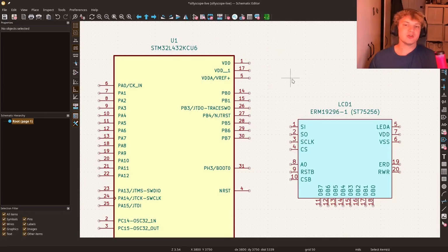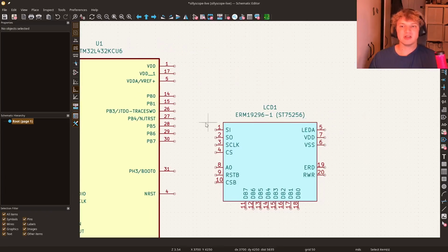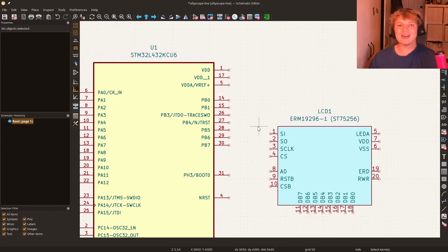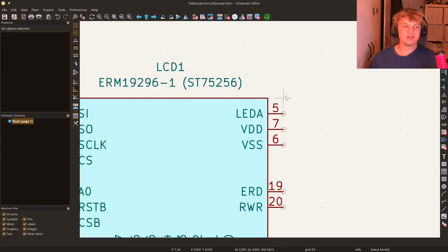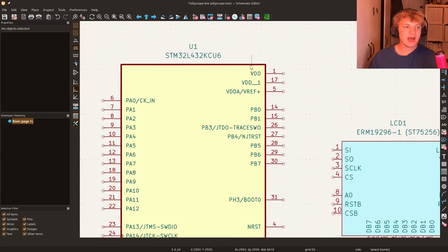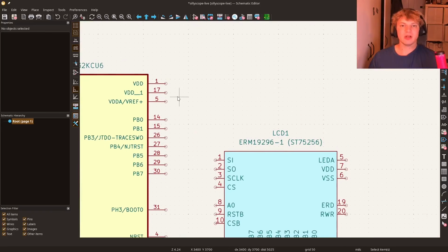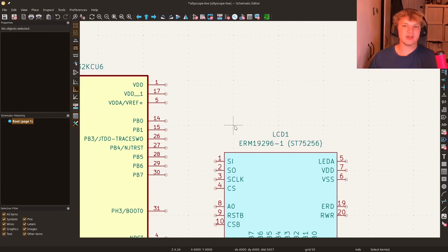And the number of voltage rails we need is going to be dependent on the differing voltages required by our components. So for example, if this MCU over here needs 3.3 volts and this LCD backlight requires 5 volts, then we'll need a 3.3 volt and a 5 volt power rail in our design. Fortunately for us, as we'll see in the datasheet, we only need one power rail in this design because this guy works off 3.3 volts and this guy works off 3.3 volts. But let's go ahead and show you where you actually find this kind of information.